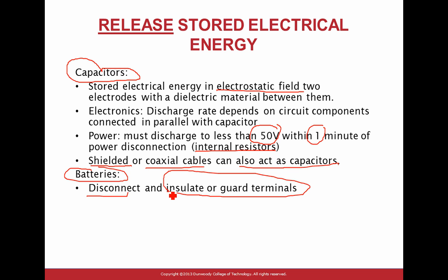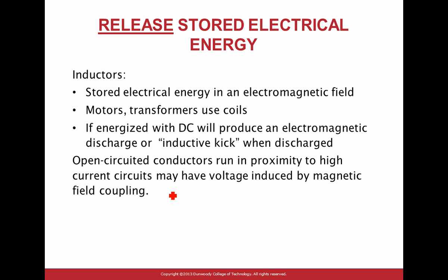You have to have a process of isolating the energy that's coming to a piece of equipment. I assume you have other sources of energy coming to the equipment that you work on, like air, steam, hydraulic, so they have procedures for isolating it. A third source of stored energy is the inductor. These are coils. If you have a coil or a motor, they store energy as a magnetic, electromagnetic field. So be aware of that. It comes from motors, transformers, and coils.